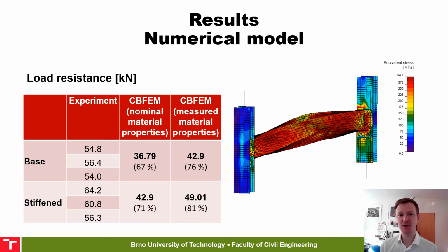It could perhaps be considered to choose a worse buckling curve for the member with stiffeners because there were welds involved. The numerical model also provides much better insight into the behavior of the substructure. An engineer can tackle the different failure modes more effectively.